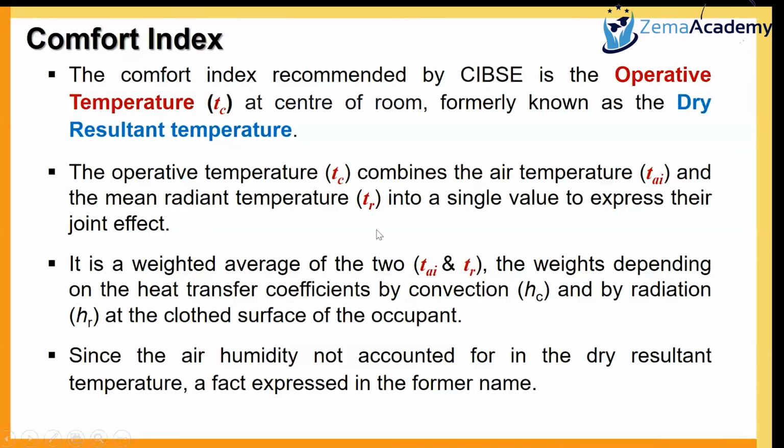Like I said previously, we are going to remove that T_ei, the equation that we just derived in our previous slide. We are going to manipulate and remove that internal environmental temperature because it's not physical. And we are going to bring in this temperature T_c because this T_c is the comfort index. We are able to define this T_c in terms of known variables.